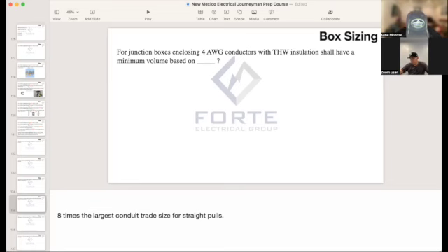Yeah, that makes a lot more sense now. So you just take your square footage, get it all figured out, multiply it times 3 VA, which is required for a single family dwelling per square foot. Then divide that by 120 volts, and that gives you your amperage, and you divide that by 15.